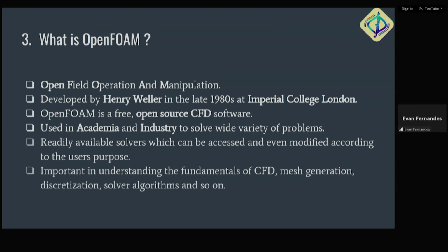But in 2015, the people who are running OpenFOAM branched it out into a foundation version and a .com version. That is basically the ESI version. That's why in the later versions you have OpenFOAM 2412, 2406, 2212, that way. The main difference between both these versions is that the foundation version doesn't get updates quite often, and the ESI version is frequently updated every six months. So you will have some new post-processing utilities or some new solvers that are introduced.